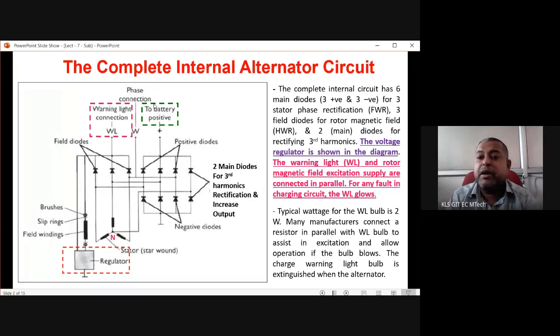So this is the main power source. This stator is the main power source, and this is the rectified power which is going to the battery. This is not directly being regulated. What we are actually regulating is, now check this left side. This is called a half bridge rectifier. So it is a half wave rectifier, not half bridge. It is a half wave rectifier.